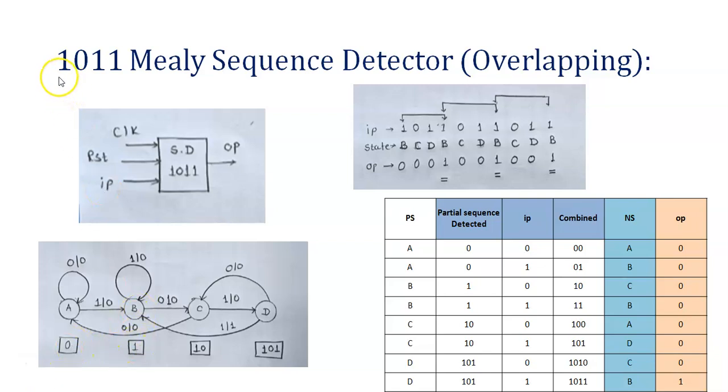The first bit of your sequence. So the first bit of your sequence is 1, and that's why you write 1 here. Now what is the meaning of C? The first 2 bits of the sequence have been detected, so you write 1 0. And on the last state you will write the first 3 bits of your sequence, that is 1 0 1.